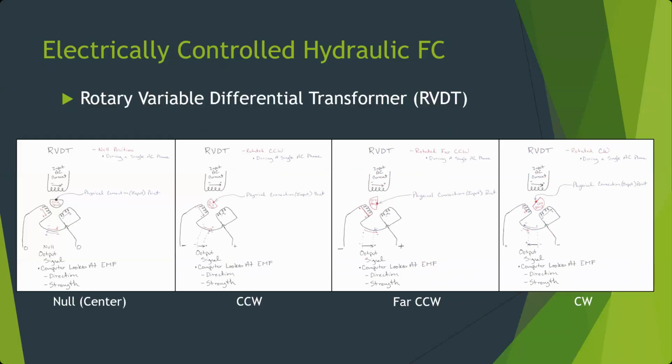They also have the ability to reverse. Variable resistors can't reverse, right? They can go lower and higher. You could always put it in the middle, right? If you have 50 ohms of resistance, that's 0, and 0 ohms of resistance, that's fully right, and 100 ohms of resistance, that's fully left, right? But if that fails, say it fails open, what do you get? Usually either 0 or 100, right? So it's going to think it goes one way or the other.